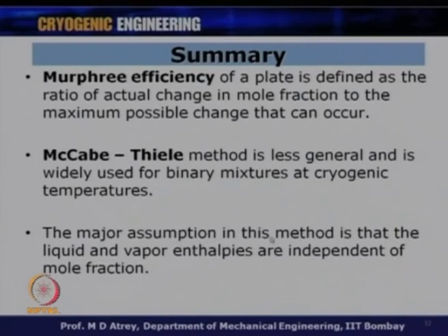The major assumption in this method is that the liquid and vapor enthalpies are independent of mole fraction, and this was a reasonably good assumption in order that we understand the variations of different parameters. Otherwise, we would have to calculate the enthalpies for different compositions for every plate. Alright, so this was the major assumption which facilitated the calculations and made it very simple.